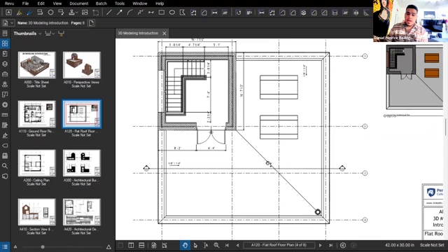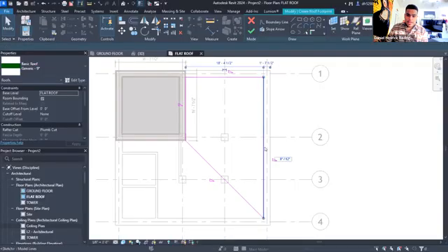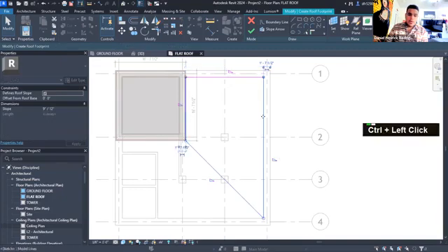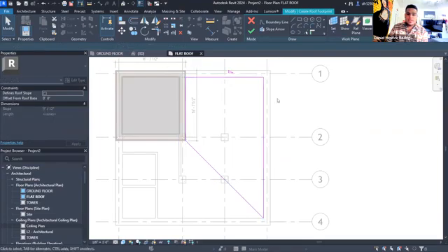If our slope was in the middle line, it would technically slope away from it, and that would create essentially a different line in the middle here, but we just want the 2 sides to slope towards the middle so that they can go to the drain. So we're gonna put the slopes in the top line, and everything else doesn't need one. So I'm gonna hit Control to add all of these lines up, and then undefine the slope.